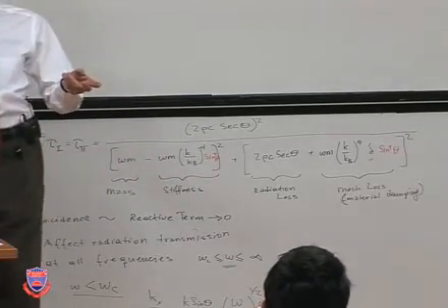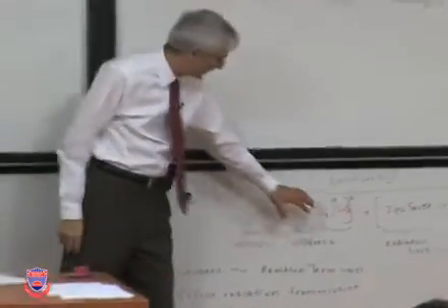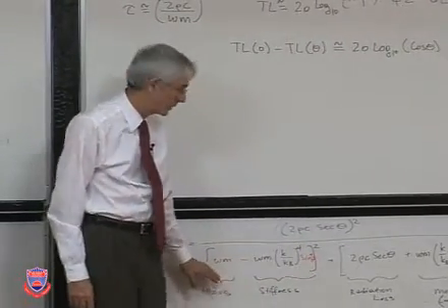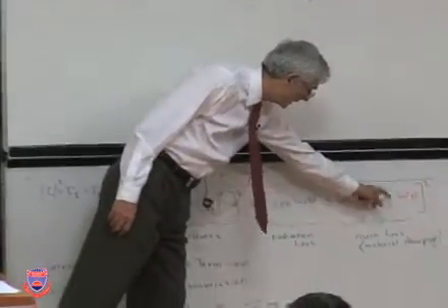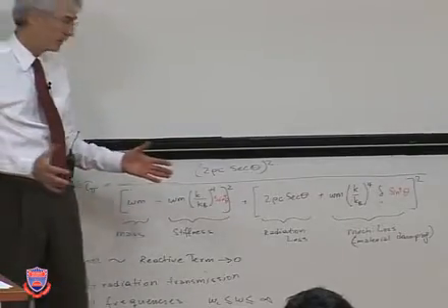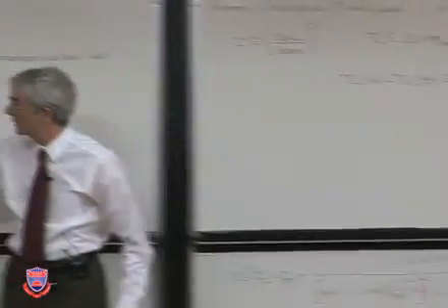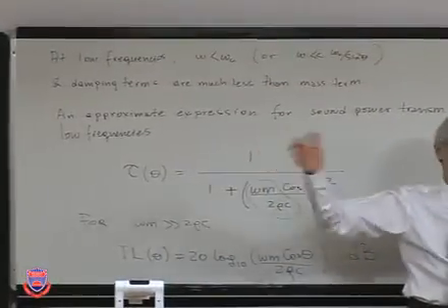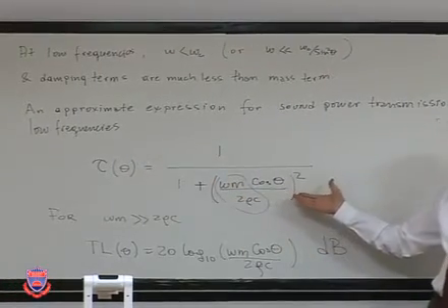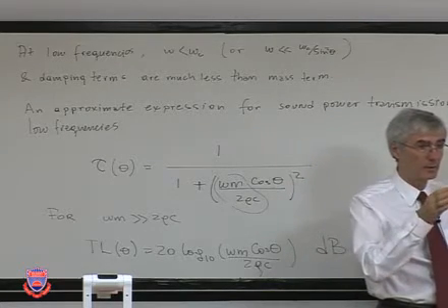These are engineering approximations. And this one particular case is when the frequency is low enough that this is negligible compared to inertia, and the material damping is also negligible. So you're left with the inertia of the plate and the radiation damping. And with those, we say for a thick wall, the radiation coefficient is given by a very simple expression, but it depends on the angle of incidence.